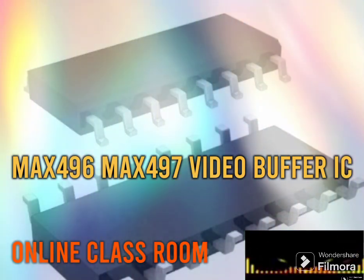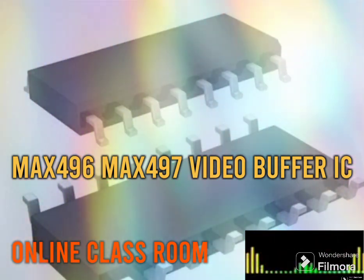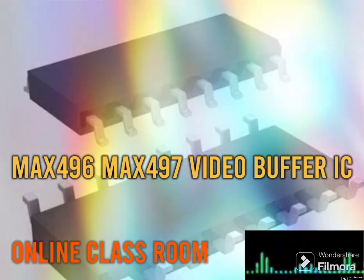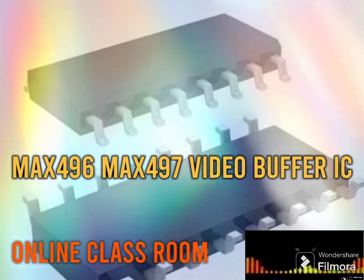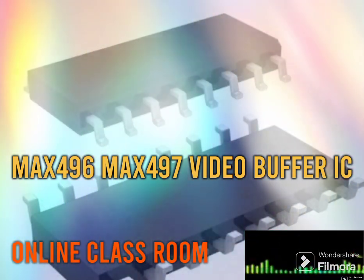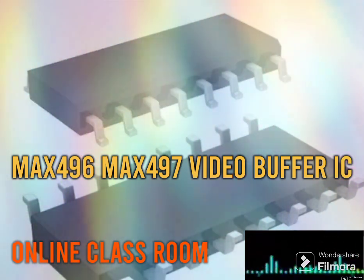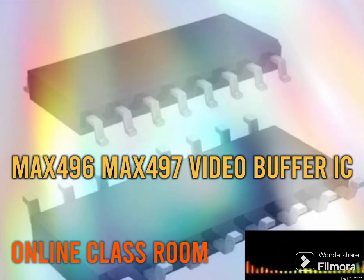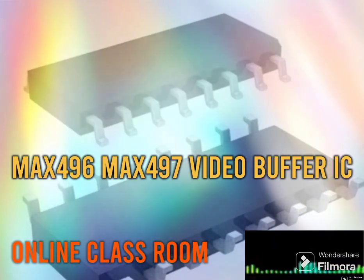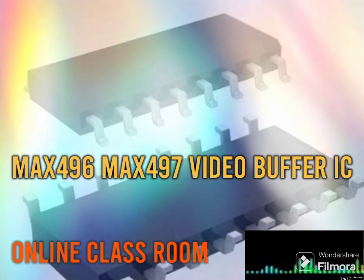The max496 is a unity gain buffer with a 375 MHz minus 3 dB bandwidth and a 1600 volt per microsecond slew rate. The max497 has a gain of plus 2 and is optimized for driving back terminated coaxial cable with a 275 MHz minus 3 dB bandwidth and a 1500 volt per microsecond slew rate. Both buffers have a high full power bandwidth of 230 MHz and 215 MHz respectively.